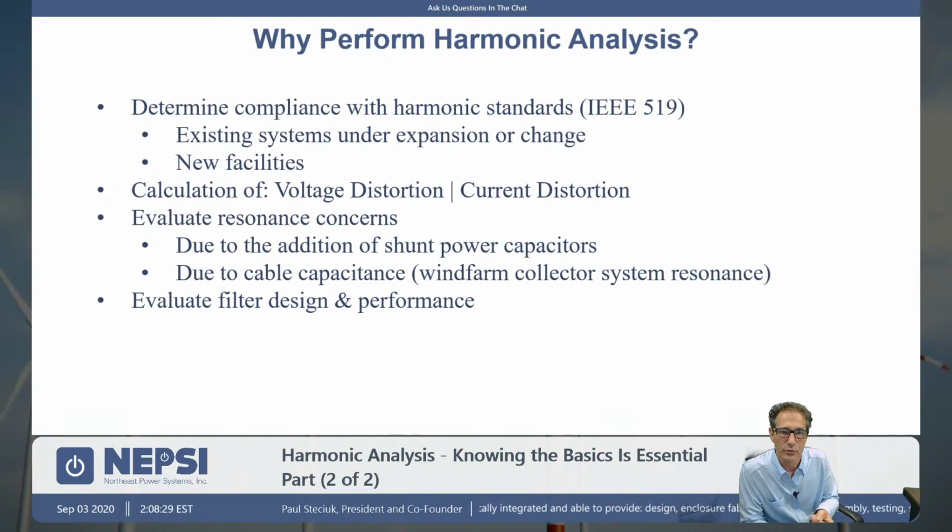Just quickly, we're doing harmonic analysis because we're looking to determine compliance with IEEE 519 or some other type of standard. It may be a new facility or it may be an existing facility that's adding, say, nonlinear load. We're looking to calculate voltage distortion and current distortion within the plant environment.